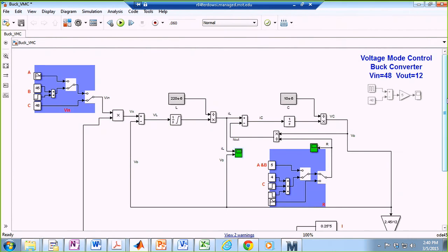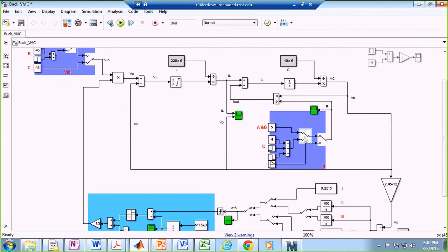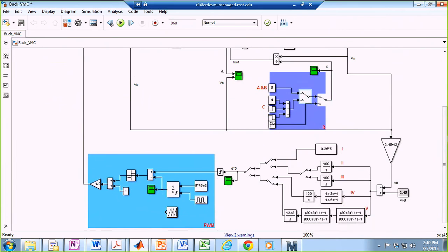All right. So this was all about basically having the system in an open loop fashion. Now what I do is I start closing the loop. For instance, my first suggestion as a compensation network is a gain of 100. I'm just making the system a little bit sensitive to the difference between the output voltage and the reference, basically.